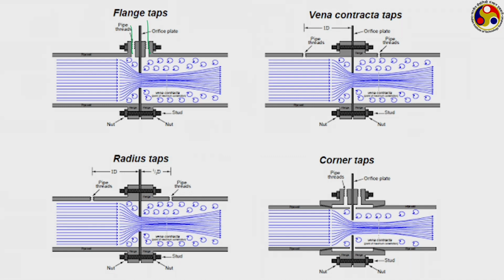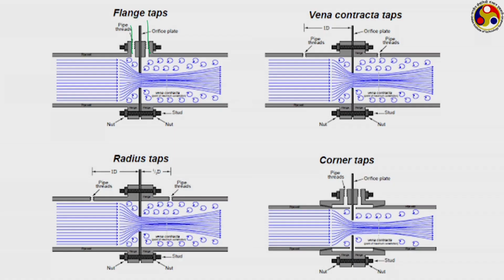For any other kind of tapping, we actually have to make holes on the walls, which technically may not be difficult, but may lead to pipe failure or leakage problems later on. From that point of view, flange tapping is quite convenient, and that is why it is quite popular in the US in particular. However, it is not suggested if the pipe diameter is less than 2 inch.